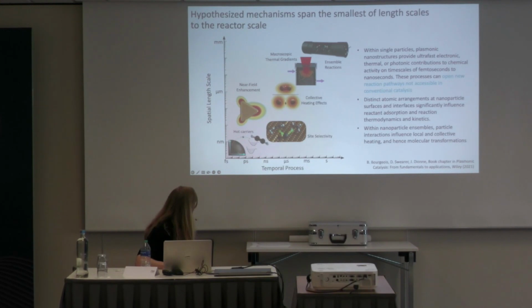Okay, if we think about the vertical axis as being energy and the horizontal axis as being probability, if we look at the Fermi-Dirac distribution function, basically the occupancy probability at T equals 0 is kind of a step function, right? So the Fermi level is where you have an occupation probability exactly equal to 1/2. And then you probably know the Fermi-Dirac distribution function starts to look a little bit more sloped as you turn up the temperature, right? So you get more thermally excited carriers.